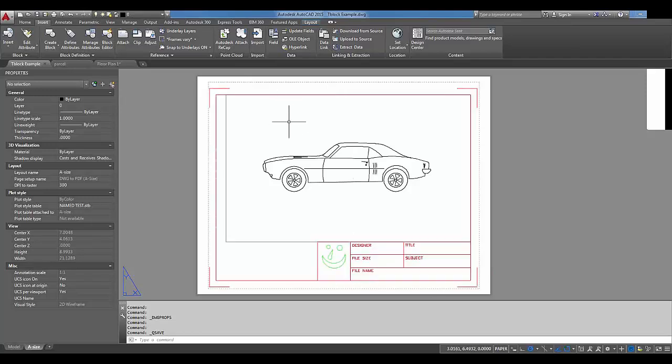Yeah. So right now I'm using this title block in this particular drawing, but we reuse our title blocks all the time. They may be XREFs or inserted as a block into another drawing. As long as the document properties have been filled out for that particular drawing, then this title block, whatever drawing it's being inserted into, would also populate the values from those document properties. Does that make sense? It does, yeah. Okay, great.